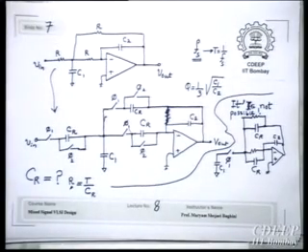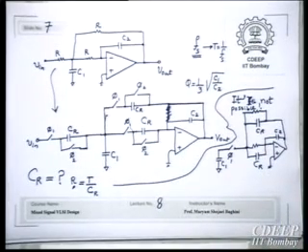If, for example, you have designed filters till now, just derive the switched-cap version. You can even start with the first order simple filter. Derive it and then simulate it. Usually it's better to keep it in the assignment also. I have given at least around 7-8 times more. But practically even twice of this is used, but it's better to keep it more than that.